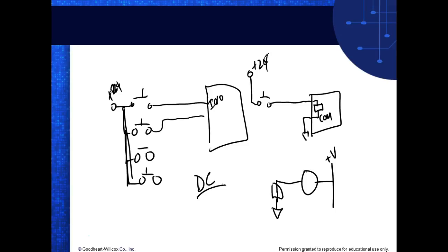To be honest, I don't think I ever ran into using DC on inputs, but it's moving that way. The PLCs are slowly moving. Most of your hybrid PLCs or your fixed PLCs have a DC power supply built in. It's 24 volts. It's not designed to run outputs, it's designed to run your inputs. We had some that do 250 volts.